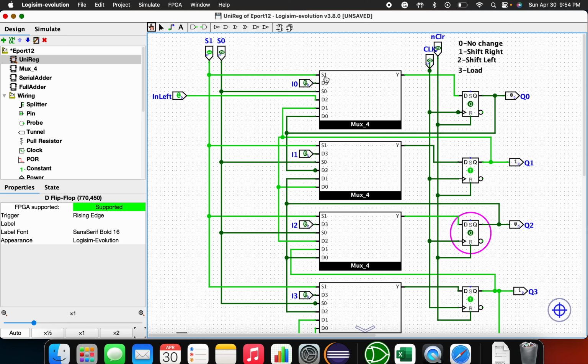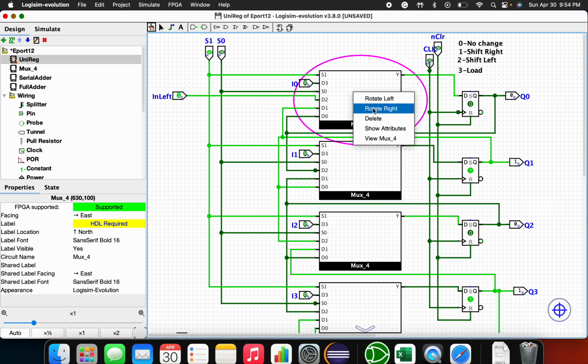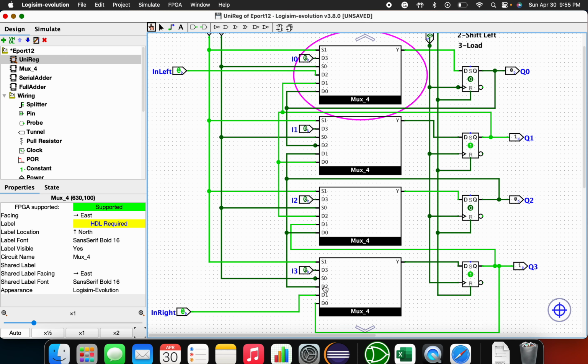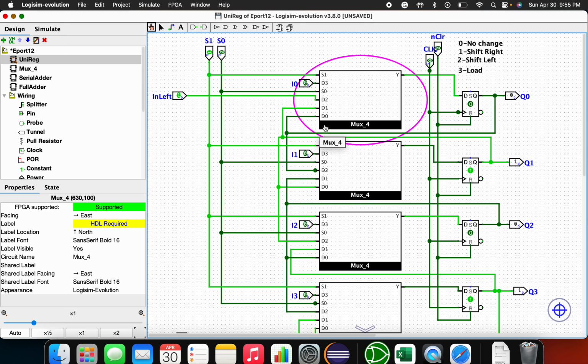And it's going to be a little bit out of order because I did not know how to make this little diagram different, but S1 is going to correspond to S1 here, and then S0 is going to correspond to S0 up here, and these are going to be our modes, and all of these multiplexers are hooked up to these modes and these switches. And then all of these D variables represent the value for that given mode.